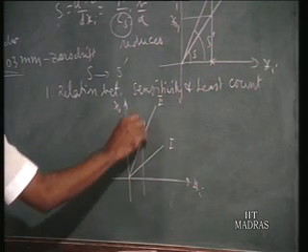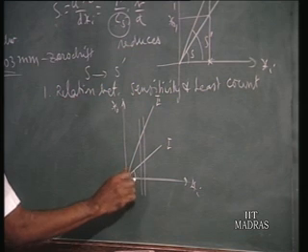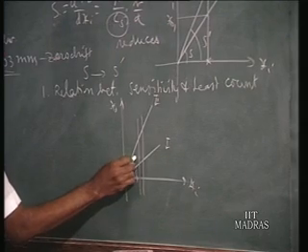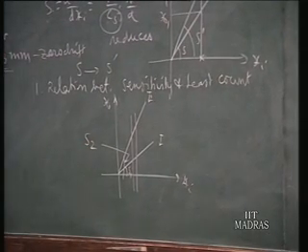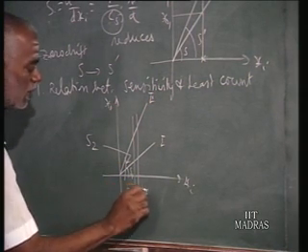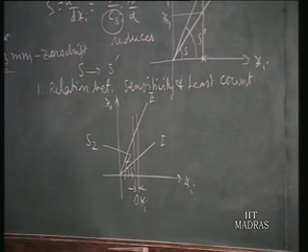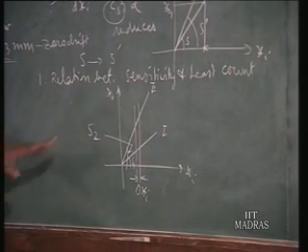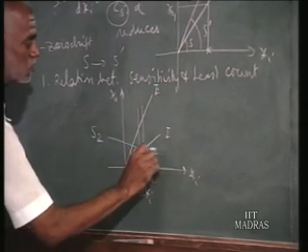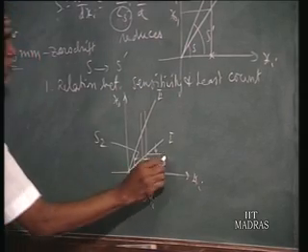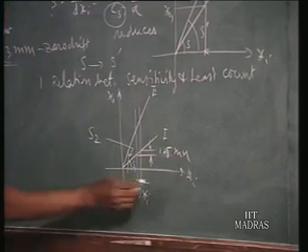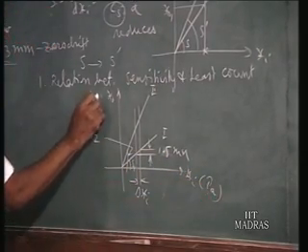Now, this is S1, and this is your S2. The sensitivity for the second instrument naturally is larger than the sensitivity for the first instrument. And suppose I give a small change in xi, say delta xi is the change in the input signal. Simultaneously I give the input signal to both instruments, and I note down the reaction of the instruments. Now, this instrument shows an output of say 1 mm, or say 1.5 mm. The input is pressure in Pascal, and the output signal is in terms of millimeter.